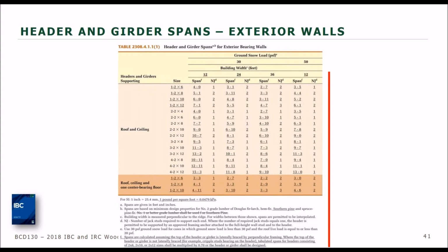As a side note, the IRC and the IBC have been different since the 2000 IRC and IBC, as well as the 2001 Wood Frame Construction Manual. So this is aligning their tables, plus there are some differences in load equations over the last 2 decades that have changed the length of the header spans. But this specific provision generally shortens the span, and it also takes into account Southern Pine number 2.